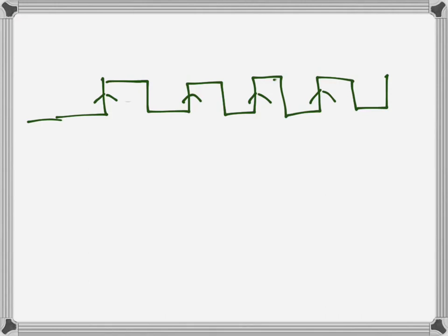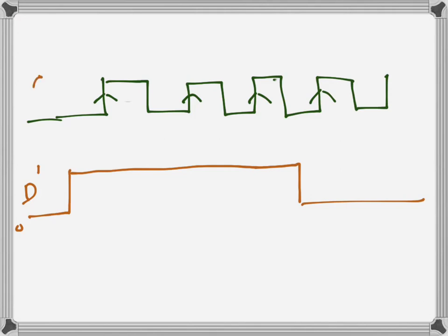So basically what I will show is, maybe I will use a different color. This is a D signal like that. It changes maybe here again and goes like that. So this is the D input. This is of course 1, this is 0, and this is our D. This is of course the clock here. What setup time says is, this is the edge. These are all the edges of the clock where the clock works. This is as well. So before that there is a certain time up to the edge where the input cannot change. This time is the setup time.